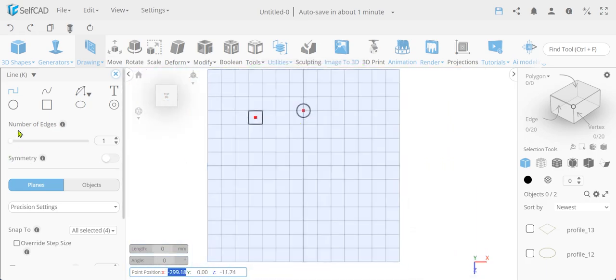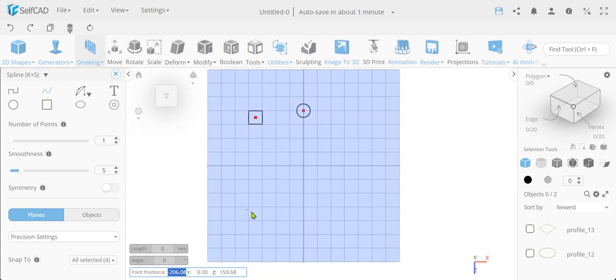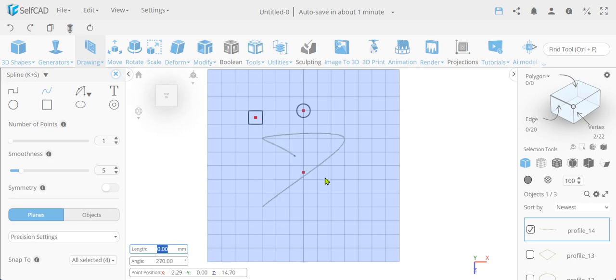Let's look at a situation where Solid Mode solves a problem that wasn't previously possible. This time, we'll use a different type of profile. Instead of using an open profile, we'll create a simple mesh-based shape. Using the Spline tool, draw a shape where different sections overlap.